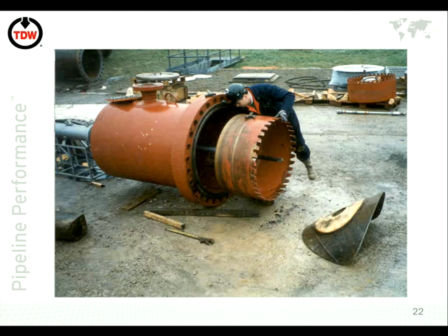So, excuse me, sir, when you cut out this coupon, what about the chips? How do you manage them? Or do they just go through with the shape? The shape which will go is just this drill size here. So you're only putting a very small hole in there. So the swarf which will come away with it will fall into the pipeline.